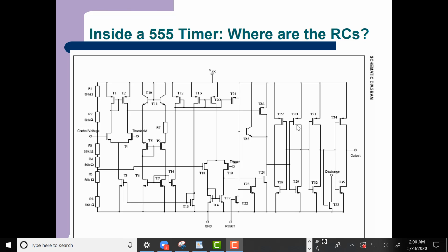We'll use small signal analysis with a model that's a little more complicated than the model we've been using. Basically it just has capacitors added to it. We'll memorize an equation for the zeros, and then we just know that every gain stage has a zero at a particular point, and that greatly simplifies it. Okay, so why do we have poles between each stage?